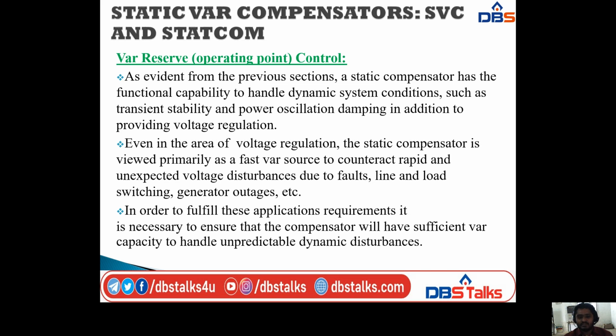Even in the area of voltage regulation, you know already that voltage regulation is defined as the ratio of the difference between no load voltage and full load voltage to the full load voltage. The static compensator is viewed primarily as a fast VAR source to counteract rapid and unexpected voltage disturbances due to faults, line and load switching, generator outages, etc.